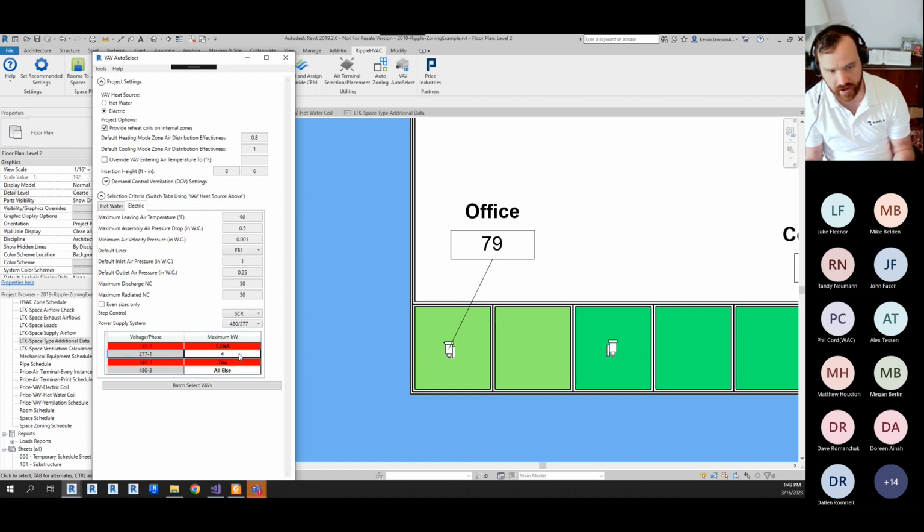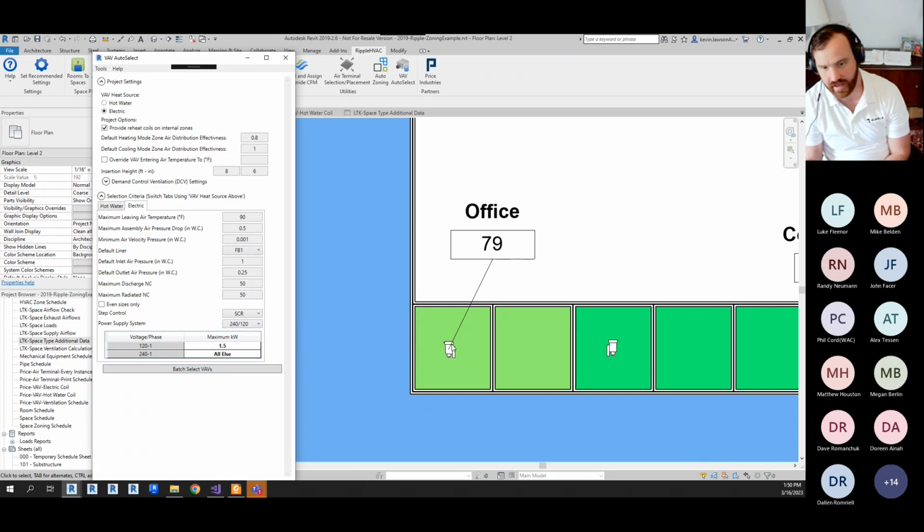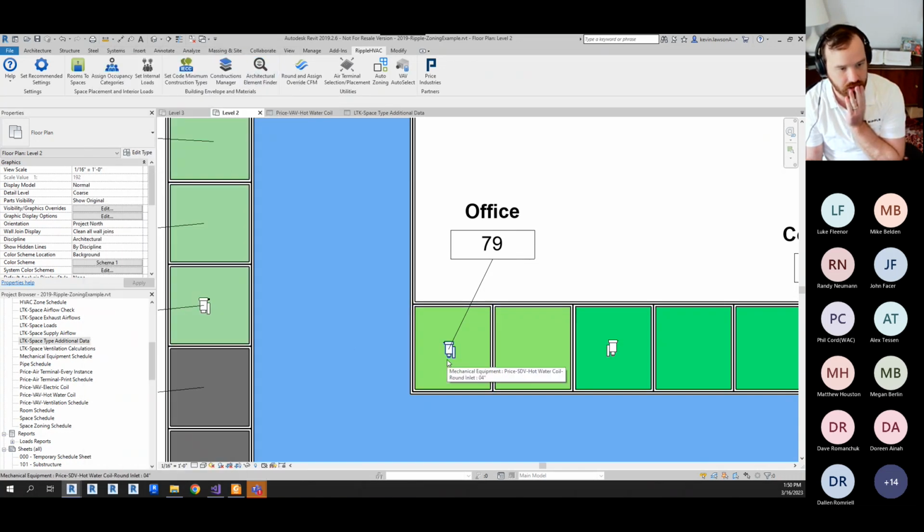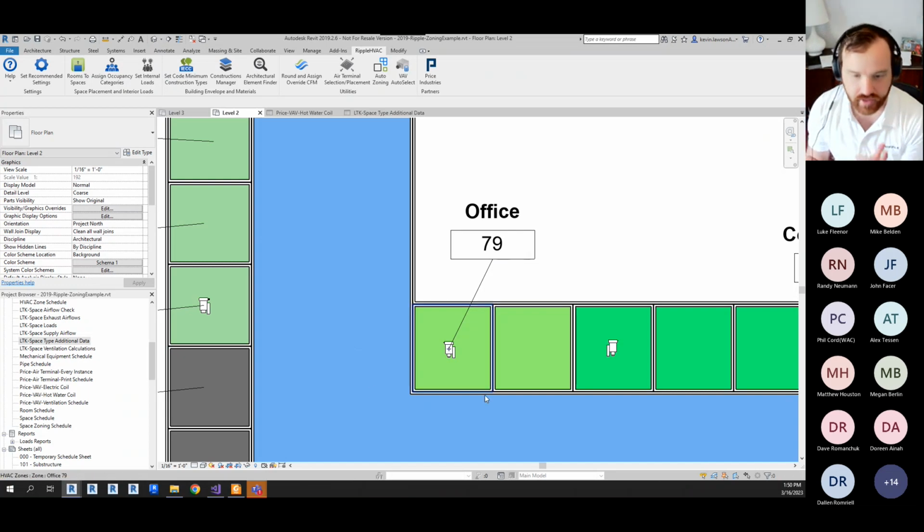And I think typically this is the way it works, is anything under 4 kW is 277 and everything else is 480 three-phase, if you have a 480/277 building. If you have something different, like a residential type, maybe you're doing 120, 240, just however you want to do that. And that'll set your coil, that'll set your voltage on your family up.